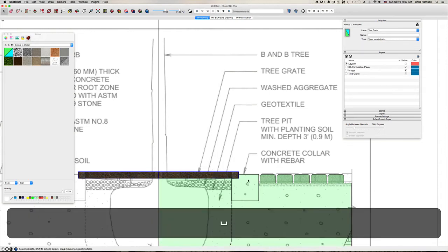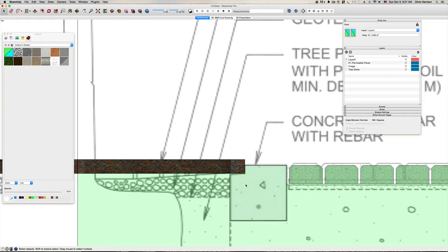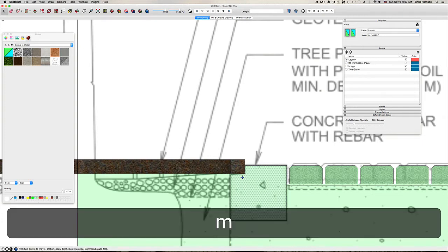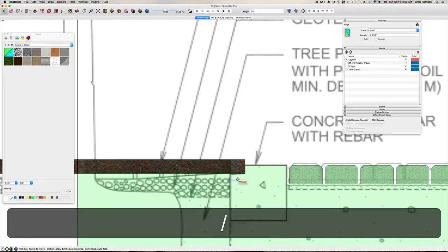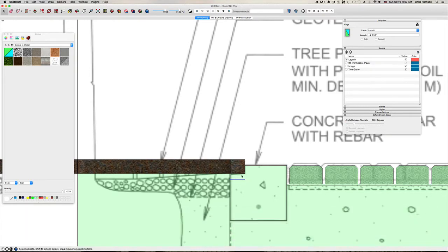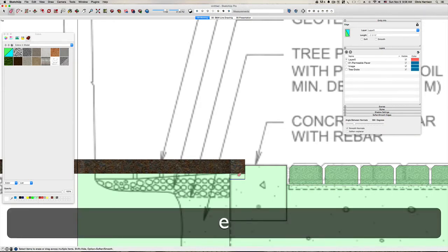I have it at 2 inches, which I think is kind of appropriate. So I'm actually going to adjust this. Just measure the distance I'm off, 13/16. So I'll just move this down 13/16. And still in 0, drawing another line in and just deleting that preview.